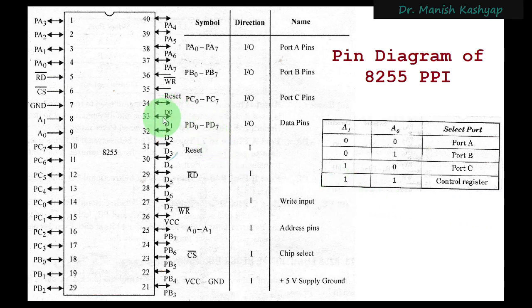Then you have got this bidirectional data line. So you can see this D0 to D7. This 8-bit data bus can be connected to this. Now you will ask how you will be able to connect your 8086 data bus, because 8086 is a 16-bit microprocessor. When we saw the instruction set, we saw that there are commands for transferring 8-bit data also, right?